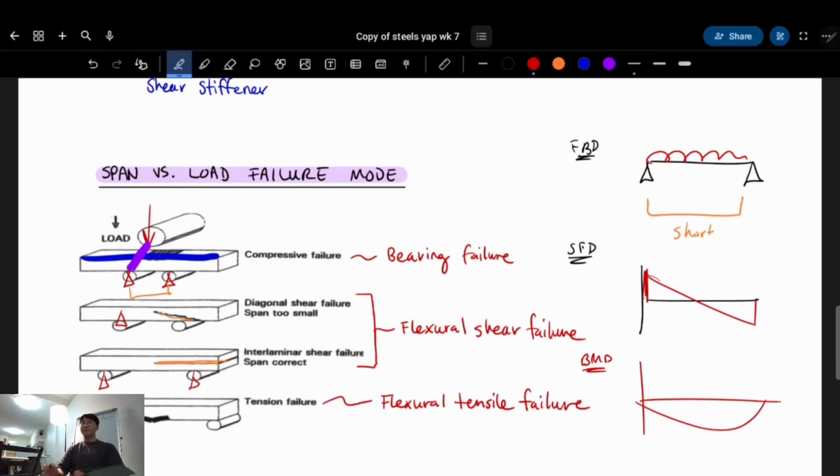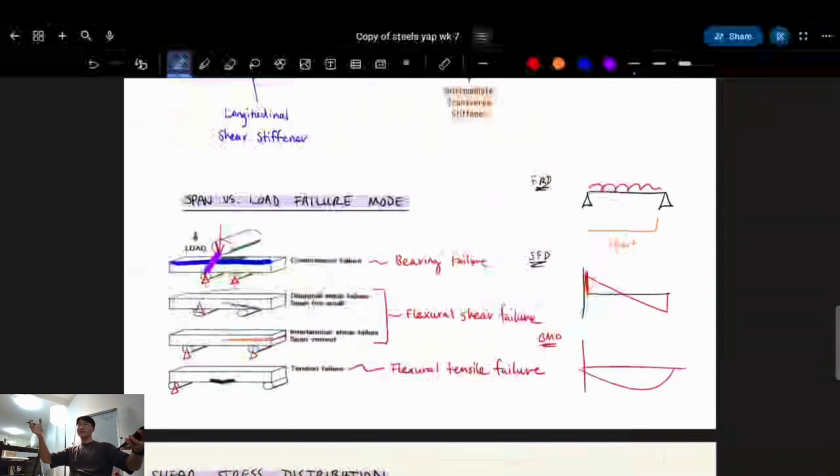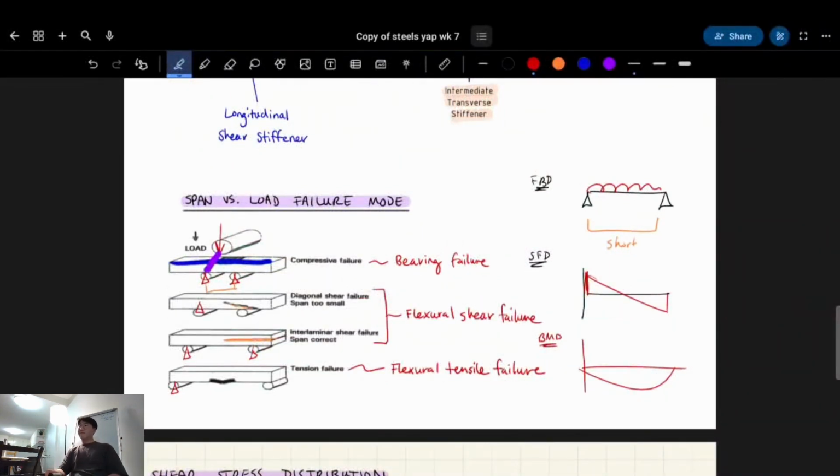Anyway, I'm kind of yapping, but do you guys get why flexure and shear are closely tied together? Are each of those failures only associated to how long they are? Can one of those failures happen at a shorter length? Oh yeah. Think of it like this, right? Bending will only really govern when your span gets long enough.